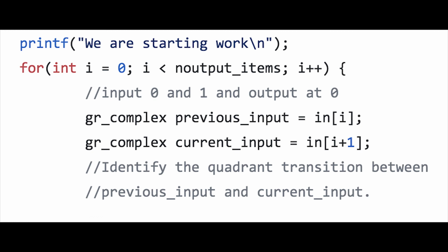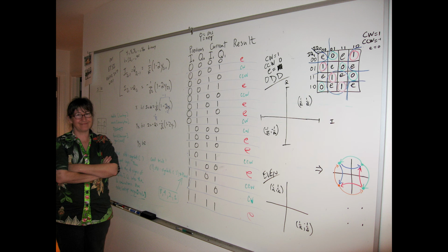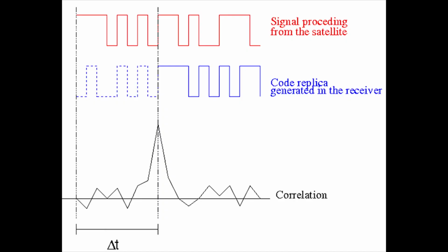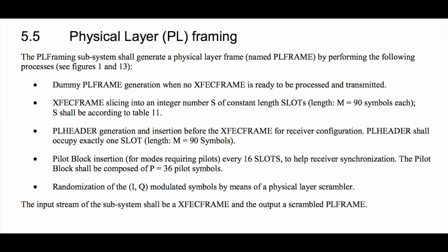Once we've figured that out and got the table indexing right, the simple unit test case we'd constructed finally passed. Assuming that the demodulation is correct, the next step from here is to take our starter frame and look for receive patterns that match it. When this happens, we will produce a tag. Tags in GNU Radio are synchronized chunks of information that are attached to samples. It is like metadata that can be used by other blocks.